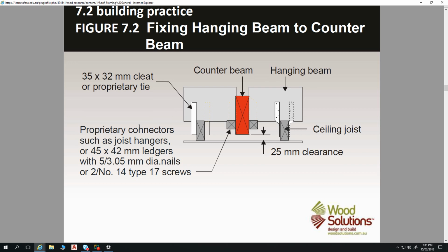You say all timber work shall be constructed as per AS 1684. And then you'll say fixings as per table this in AS 1684, for example. So we don't go specifying all those fixings, and unless we're carpenters, we don't necessarily need to know them.